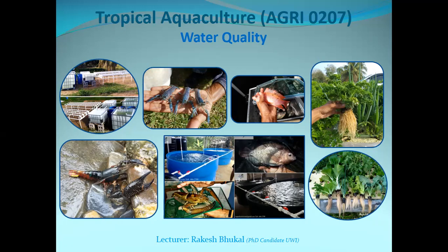Your biological filtration component will convert your ammonia to nitrites to nitrates. Ammonia and nitrites are toxic to fish, and those are two water quality parameters that can have detrimental effects on aquatic organisms. Nitrates, not so much. So your biological filter is really just a way to maintain your water quality. The mechanical filter has the same purpose. It helps to keep that water quality within a good range.